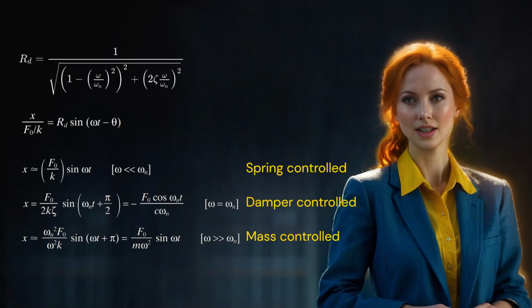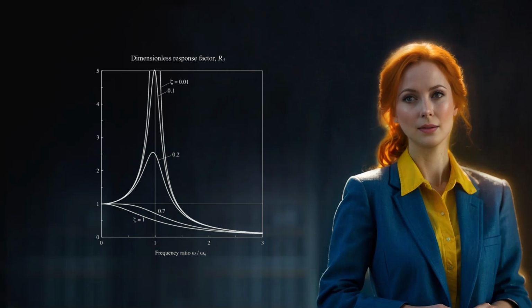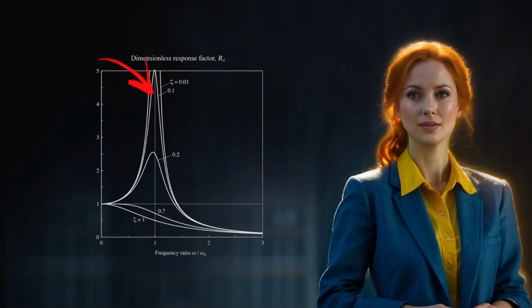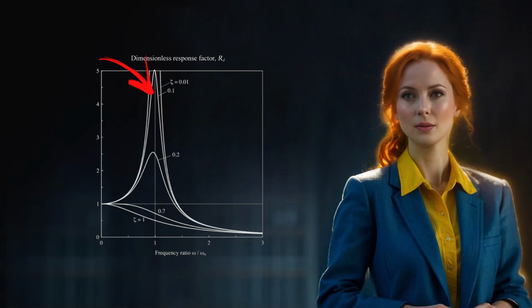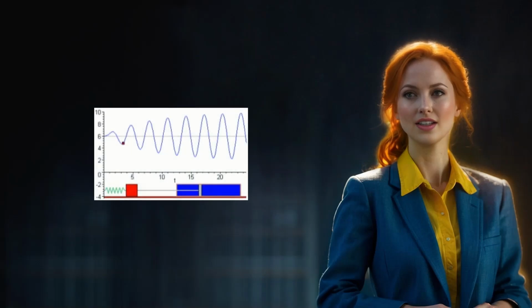This relationship provides the key to understanding how the mass and spring work together to impart a distinct resonance behavior to the system. When the forcing frequency omega becomes close to the natural frequency omega n, the system exhibits rampant oscillation. This resonance phenomenon is a result of the mass and spring exchanging the energy in a periodic manner at the natural frequency. It's the damping that controls this resonance that could otherwise lead to a divergence, where the vibration could spiral out of control.